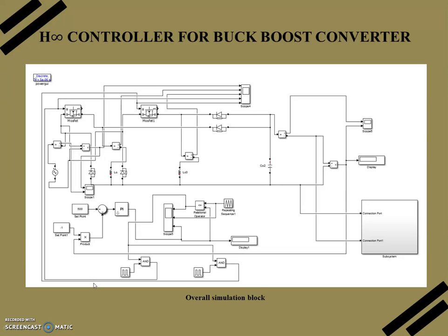Usually a conventional DC-DC converter has high current stress, and similarly high ripple in both the input and output parts. To overcome these disadvantages, an interleaved buck boost converter is used. An interleaved buck boost converter is nothing but a parallel connection of buck boost converters, which gives greater advantages like greater reliability, improved power quality, and lower losses. The system can be improved by interleaving the operation of the parallel converters.